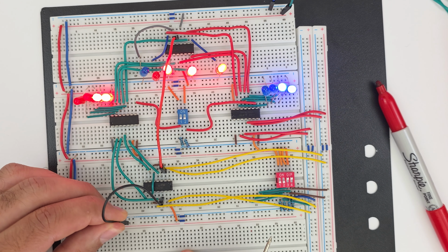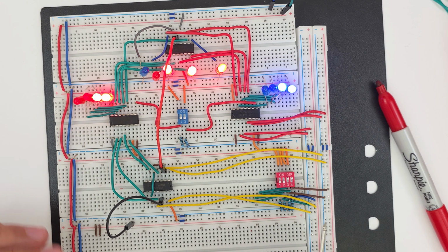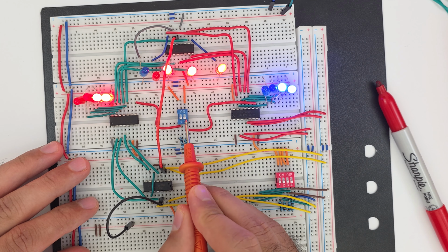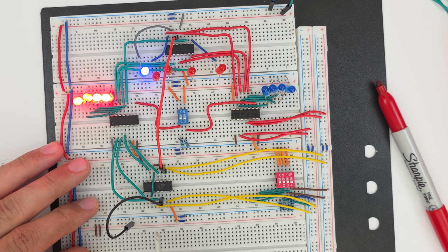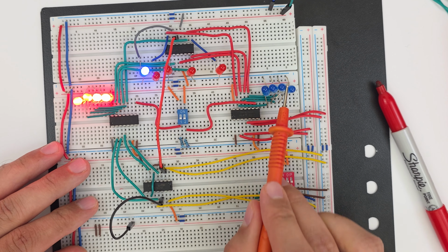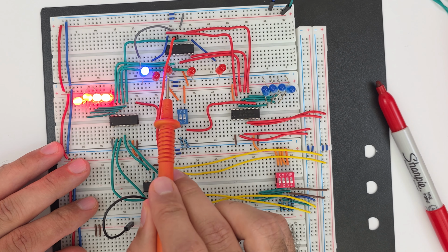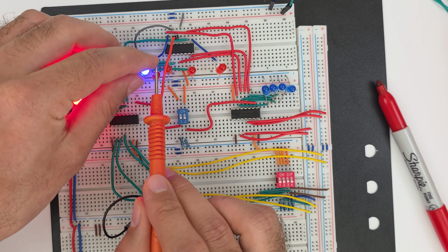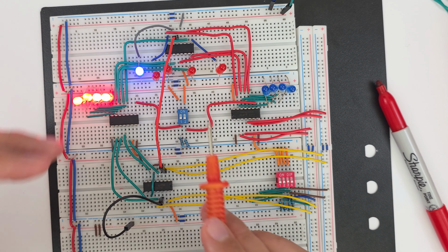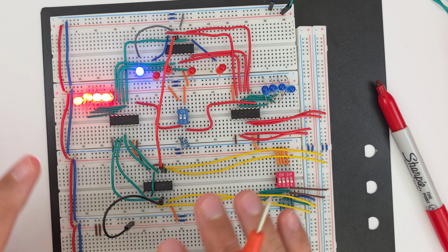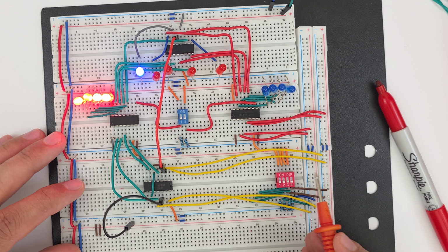Let's now move this to the VCC, and now we should see the output of the subtraction. So I'm going to start again with 0 and 0. So this value is negative 0, right? So as you see here, 0 minus 0 is 0, because this is the carry out. The carry out is on because this is like the negative 0. I know that there are positive and negative zeros, but this is how it is represented by the 2's complement.